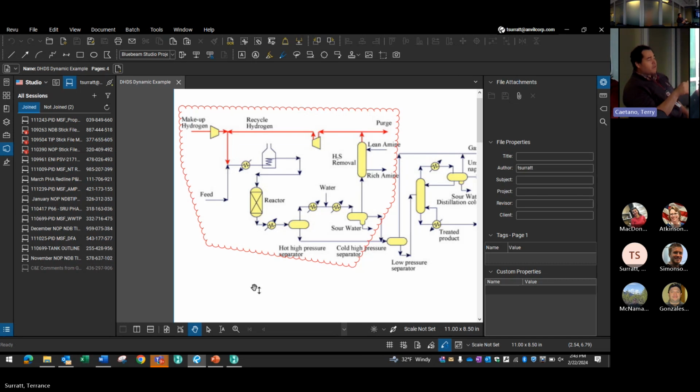And so what we were looking at was a few things. We were looking at the potential to overfill one of the separators. What would that hydraulic pressure look like if that vessel had overfilled? We were looking at what would be the settle out. So if you stop flow in and out, how does the pressure balance out in the system?